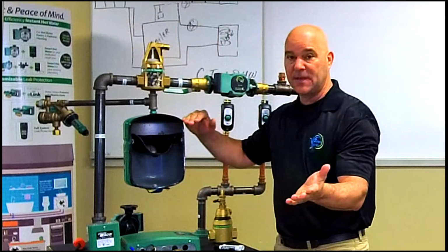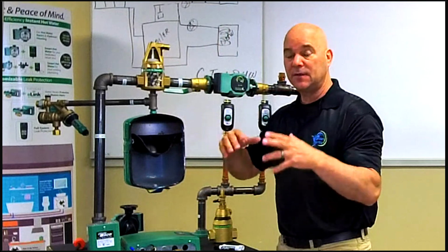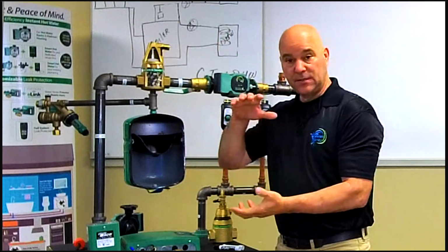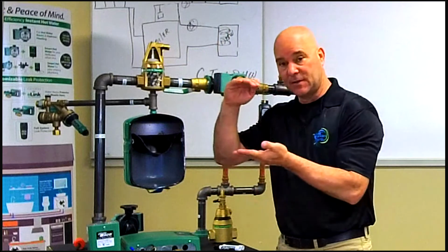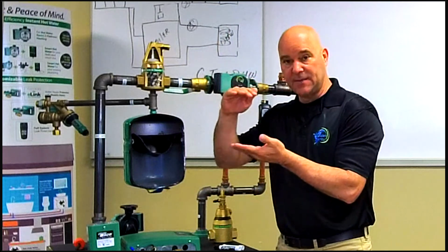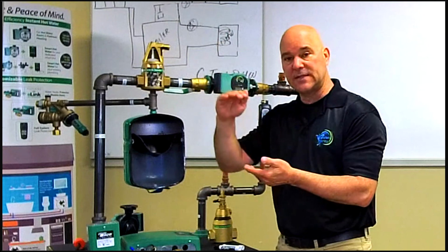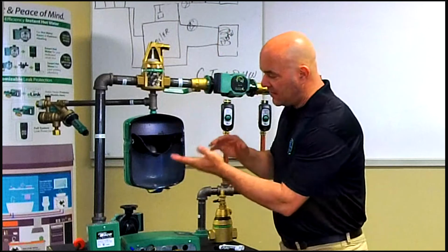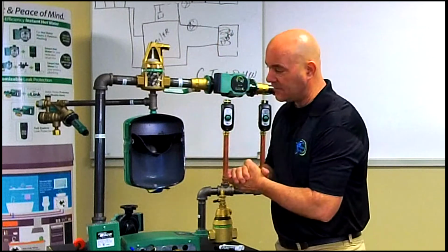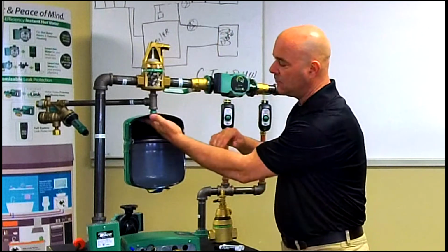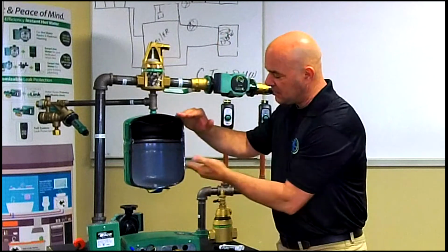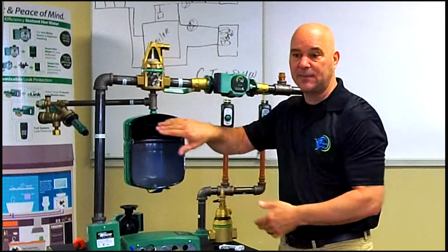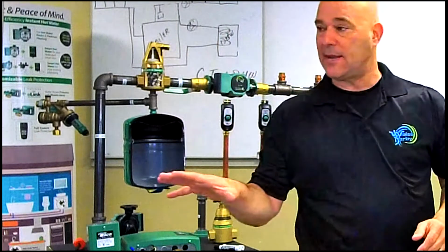And this goes the same for a domestic hot water expansion tank. You're putting one on a 40-gallon direct fired water heater. You need to set your incoming pressure and your air pressure to be close to the same, so that when we expand the water in the tank, it has somewhere to push back into the system. Okay, so that's what will happen. That's what will cause us to fail prematurely. We have to have equal pressures, system pressure and air pressure, on this expansion tank to allow this diaphragm to do its job properly. We good on that, Jim?